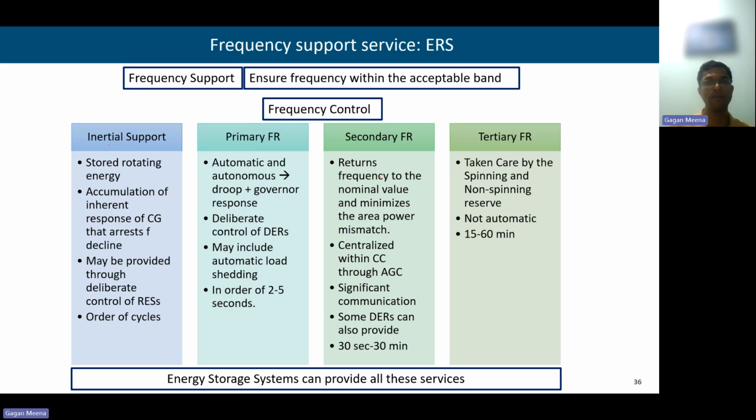And this is not automatic. It takes between 15 to 60 minutes. Whenever this frequency service is required, the spinning and non-spinning reserve generators are called upon by the operator to provide this kind of service.